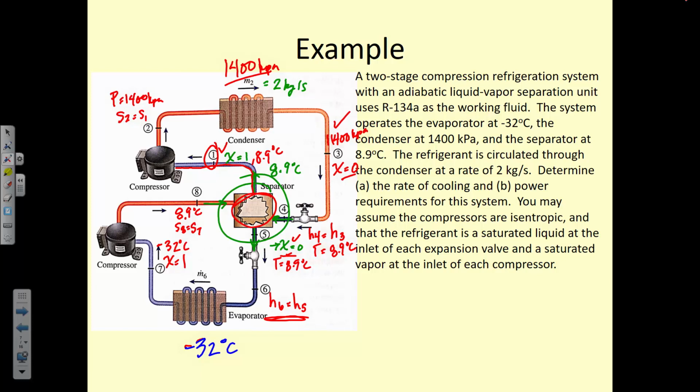Yeah, this is the one everybody had trouble with, for the heat pump. Is it QL or work? Wait, what is that? QL is the rate of cooling. Q dot L, right? Q dot L is equal to M dot times QL. Where's QL? It's the lower part, the evaporator side. Okay, so this is going to be your QL. This is going to be your QH.